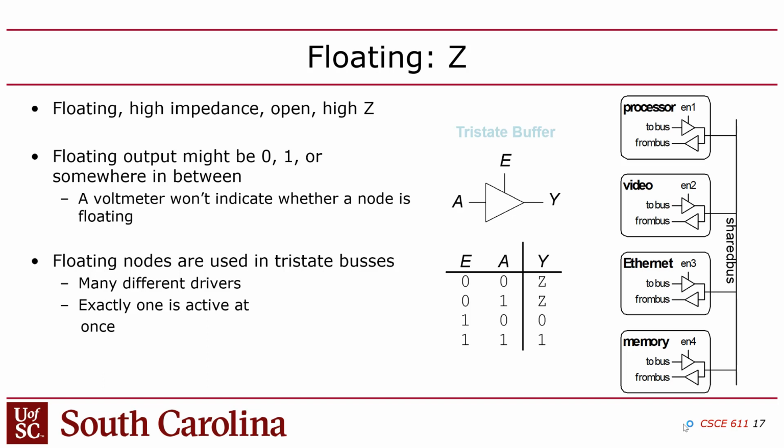You can also drive a signal to Z if you're intending to make a tri-state buffer, which is where you can actively disconnect an output. That happens for bus-type things like I²C, when you have a multi-master bus where you want to be able to have different entities drive the wires. You can use Z for that. We won't be using that in our designs in this class, although I expect you to know what it is in case you see it. So Z is high impedance.